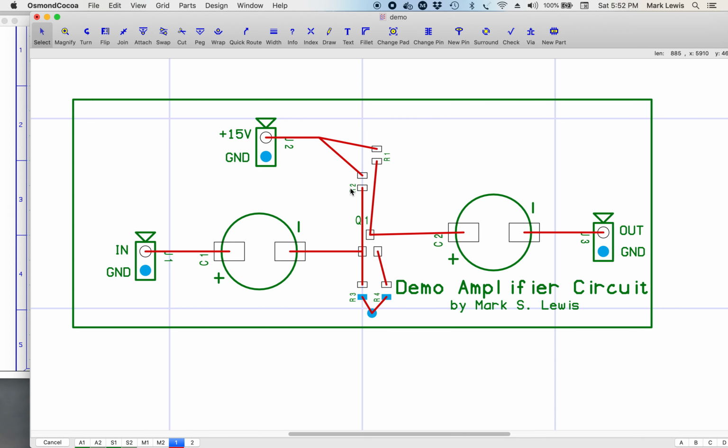In general, one of the rules is you don't want the text to be smaller than, they say, 50 mils. I would say 35, because I think the labels for the resistors are about 35 or 3 or 4, and they're still readable when you get the circuit board. So I'd say 35 mils is probably about the smallest you'd want to go as far as the text size.